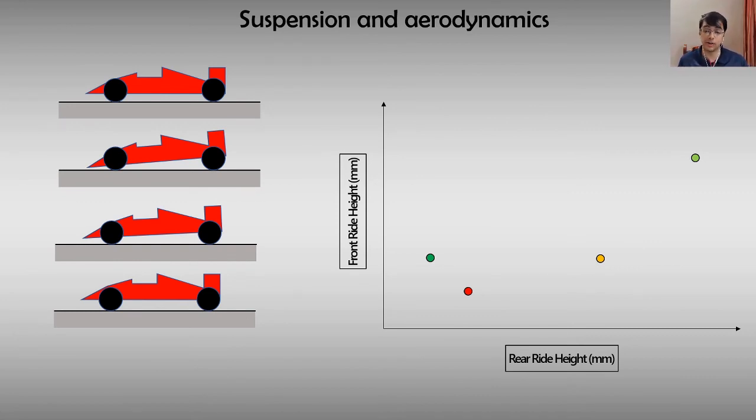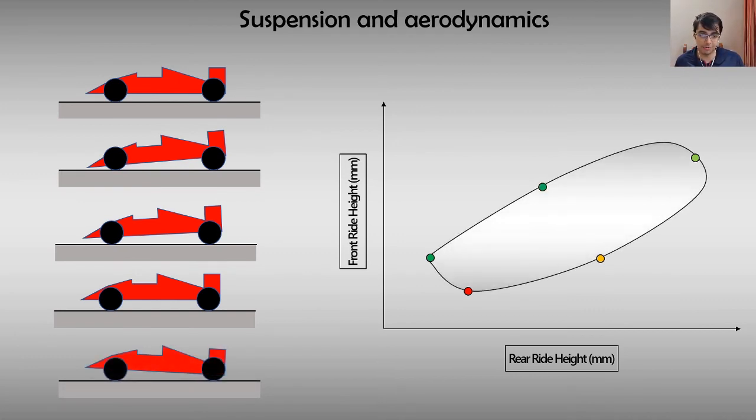And that's why the rear will drop and the front slightly raises. But of course, initially the rear will drop and the front will raise, but since the downforce starts to act, the front also gets pressed down, which is why here you can see the front ride height is ever so slightly lower than in the previous case. But the rear ride height is of course dropped a lot. So this is what a cornering situation is.